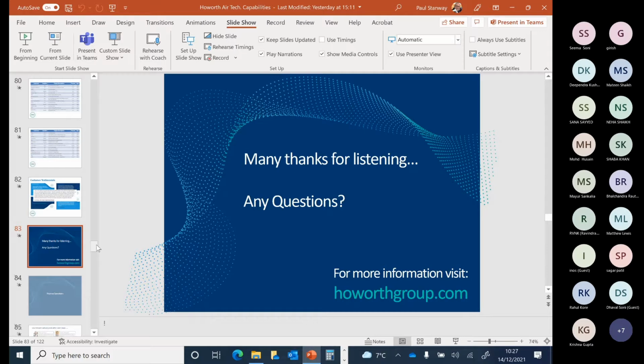Yeah, absolutely. So again, that's quite a common request now. So the input air or nitrogen is often used. So we look at dry compressed air or nitrogen. Nitrogen will give us quite low humidity within the system. So it all depends on where you are in India, because the humidity could be different at different parts of the country. So these are the kind of things that we'd have to look at.